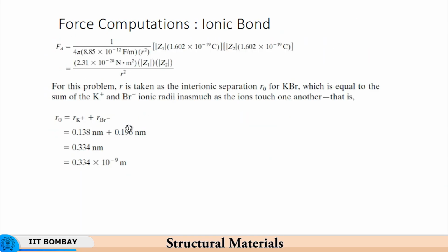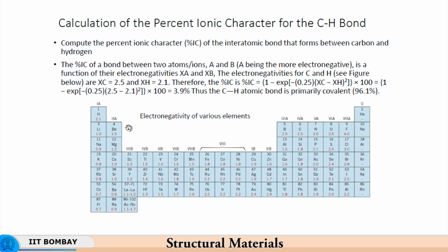So, now if you look at the periodic table involving these electronegativities, you have carbon 2.5 and silicon 1.8. So, there is a very small difference in the electronegativities as opposed to, let us say, oxygen 3.5 and magnesium 1.2. So, there is a significant difference in the electronegativities here as compared to silicon and carbon. So, naturally the magnesium oxide will have much higher ionicity as compared to a silicon carbide bond.